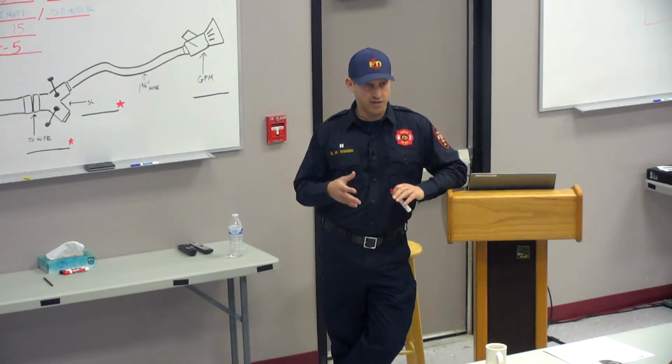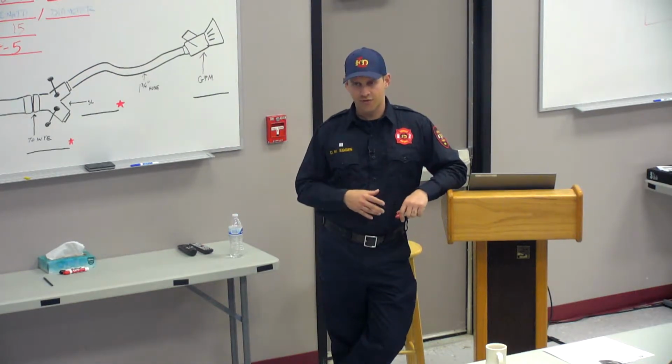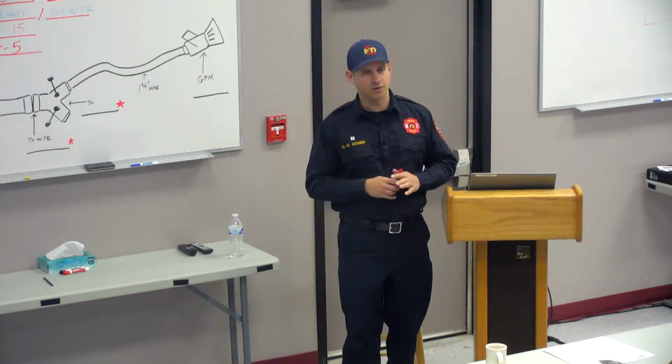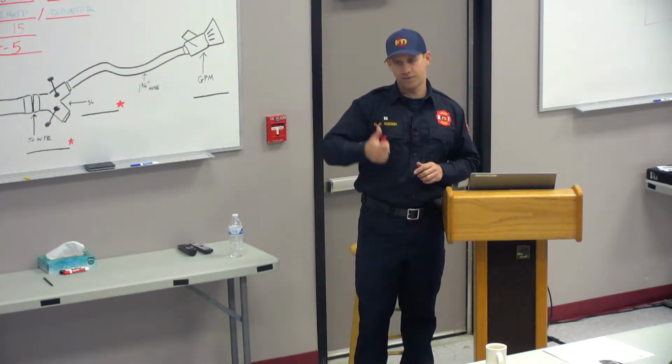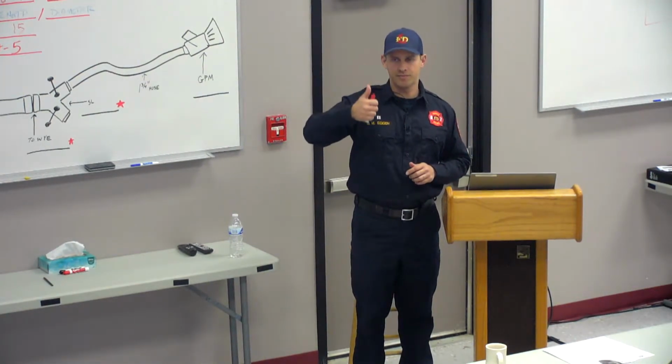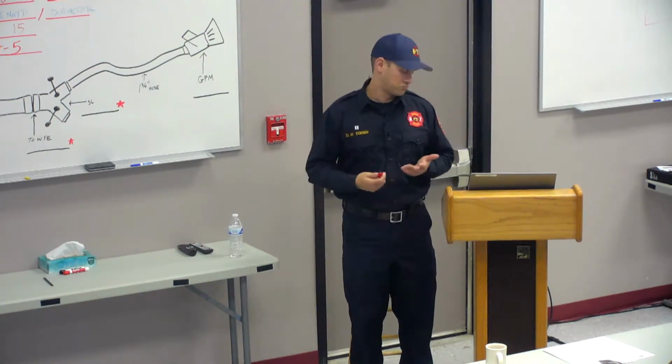So just understanding the difference, right? Again, stuff you may have heard before, not a big factor, but that's why we don't really consider any friction loss when we're pumping 5 feet up to that deck gun. It's not needed.